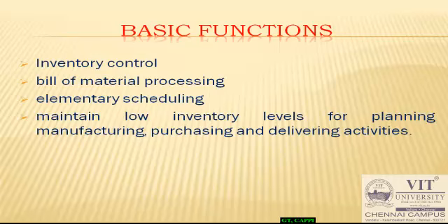So for MRP, the main important inputs are the BOM, that is the bill of material, and scheduling. Based on the available resources, materials and also process, you have to prepare one schedule. Based on that only, you can calculate the materials requirement. Suppose you have 1,000 components in order, and per day you can create 50 or 60 components. To manufacture those 60 components, what will be the schedule? According to that schedule only, you can procure the raw material.